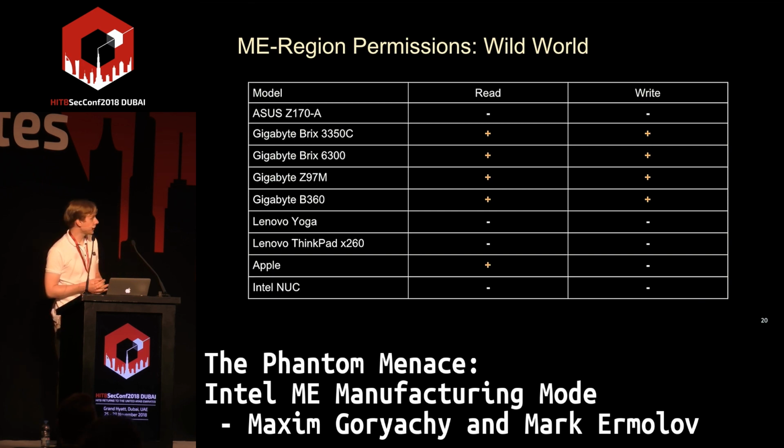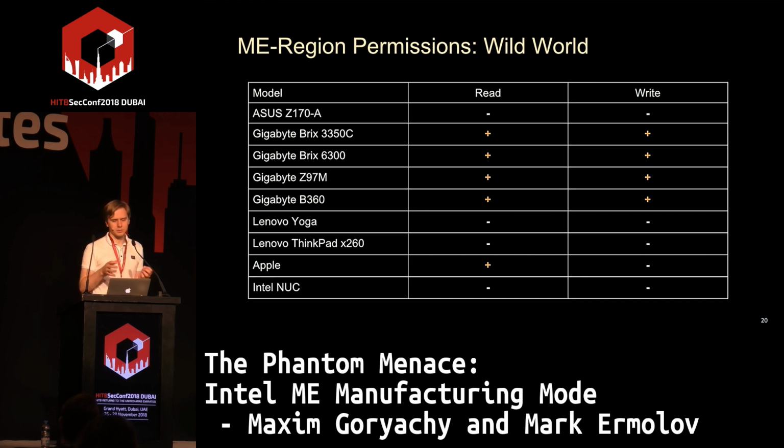Interesting that Apple gives read access to the ME region, and we didn't find any security issue in this fact, because all ME security-sensitive data is signed or encrypted, and if you can read this region, you couldn't decrypt the data in, for example, the SPI, on the MFS partition of ME, the file system of ME.